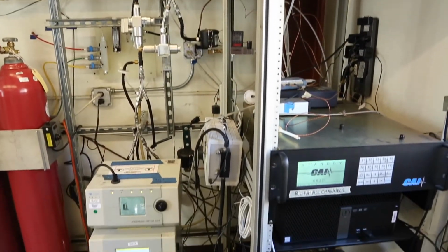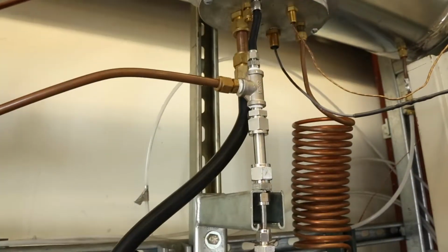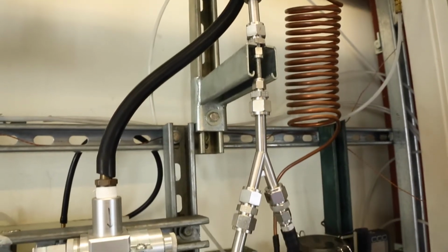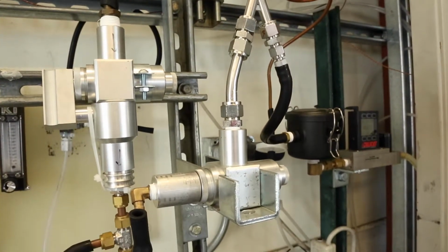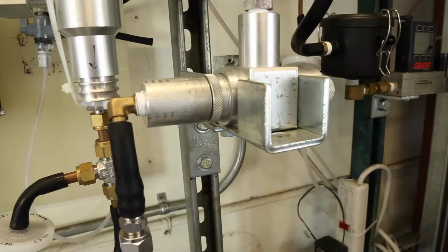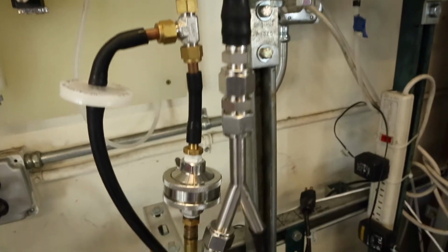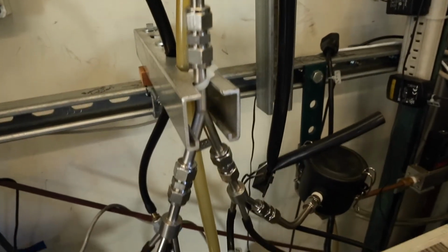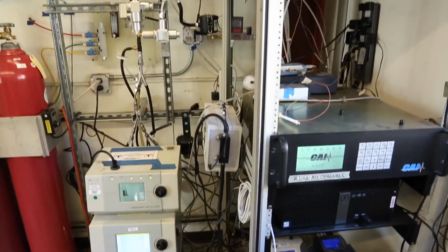In addition to measuring real-time fuel and water mass, our laboratory has developed a real-time aerosol sampling system. This system has the capability of measuring real-time size-resolved concentrations of aerosols from 5 nanometers to 20 microns in diameter, along with black carbon and PM2.5 mass concentration. We developed this system to enable rapid cookstove design evaluations and to further our laboratory's research mission.